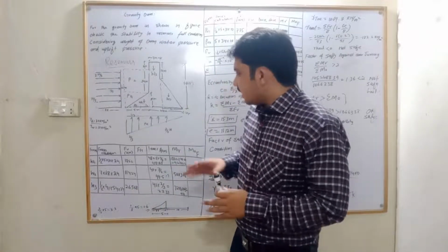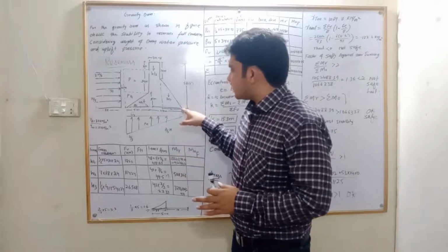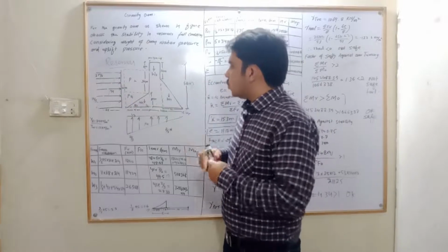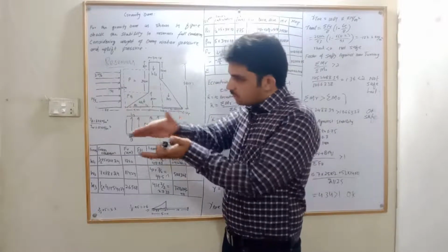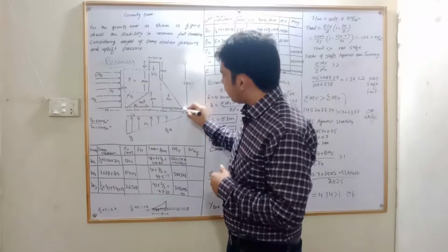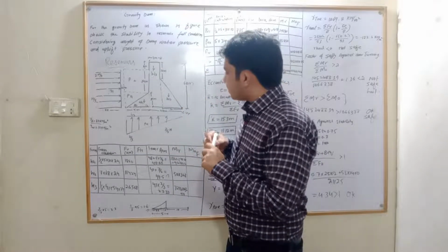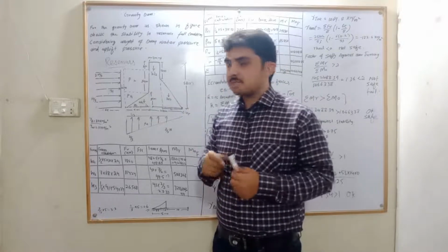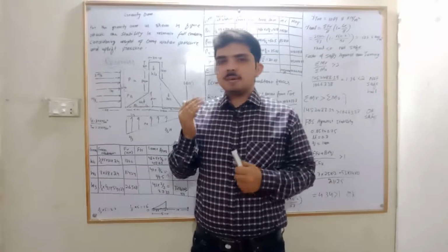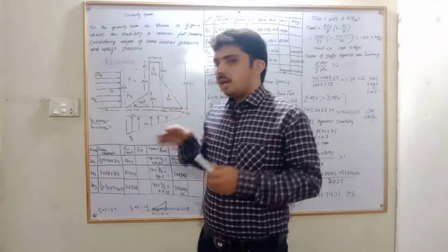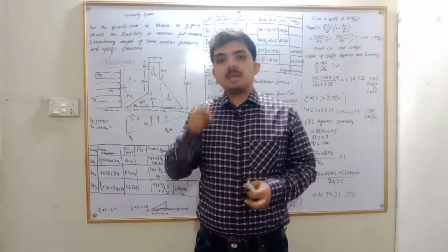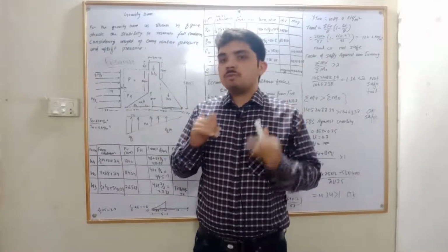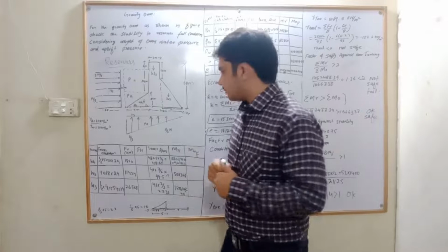Now it is necessary to know that, for example, this is the dam end portion. This is the downstream side and this is the upstream side. All of the forces will have a lever arm at that point, because we will consider this point for the lever arm. From this point we will now find the center of every triangle and every rectangle, because when the load comes on the dam, this is an irregular area, and the summation of all load and the maximum concentration of the load will be here, at a center which is unknown. We need to find the center.